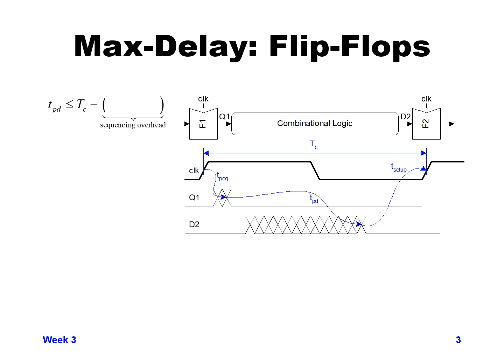Now, we have two things that are set basically by the flops that you're using. Depending on the type of flop you're using, each flop will have a certain amount of setup time that's determined by just the structure of the flop and how it's clocked.